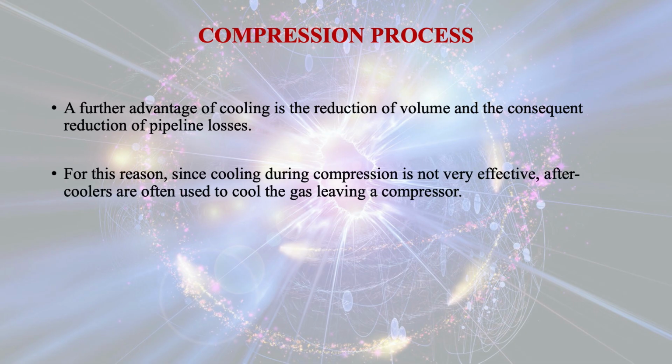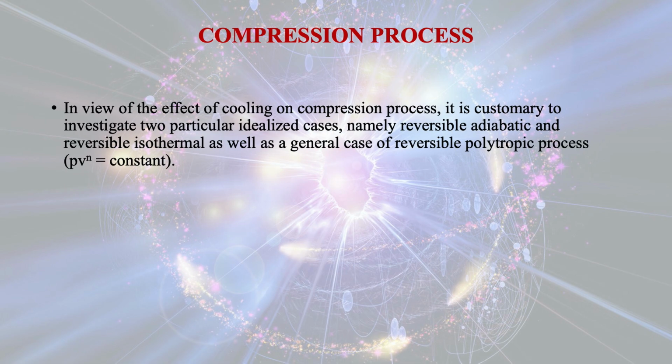For this reason, since cooling during compression is not very effective, aftercoolers are often used to cool the gas leaving a compressor. In view of the effect of cooling on the compression process, it is customary to investigate two particular idealized cases, namely reversible adiabatic and reversible isothermal, as well as a general case of reversible polytropic process whose equation is PV^n = constant.